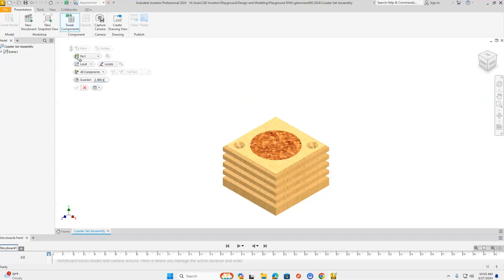I like to kind of move it and get it locked into one spot. So what I would like to do is right here in the bottom part of this menu for the mini toolbar, you're going to make sure you put a check mark in front of Pin Mini Toolbar Position. And that's going to help keep it in one position, otherwise it's going to keep moving around on you. Okay, so check mark in front of Mini Toolbar. Also, where this option says All Components, we're going to click on that pull down arrow there and select No Trail, so we don't have trails going behind each one of our parts.